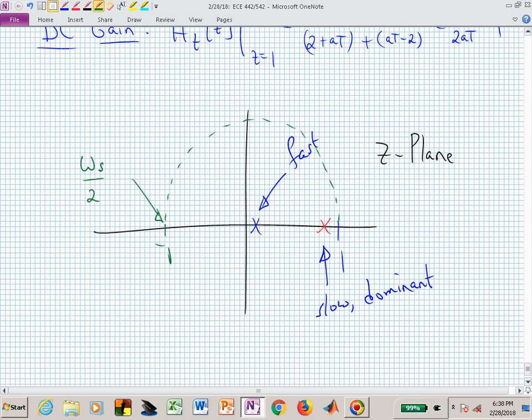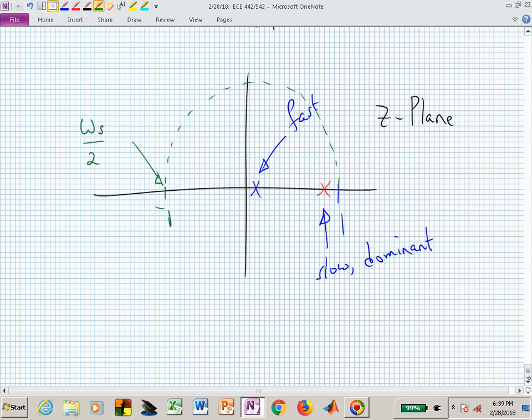Do you see why I'm saying -1 can be viewed as fast and 0 can be viewed as fast? We're actually going to learn that we probably don't want poles between 0 and -1. Those kind of give us nasty behavior. They're stable, but they kind of give us weird behavior. Now, before we get too far off, did that help answer your question as far as fast? And then you didn't have to worry about seeing what you missed before, right?